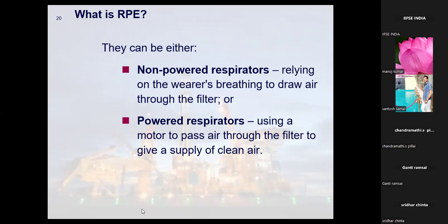19.5 is the minimum oxygen requirement level, but the quality of air, what we say is class D. Now, this class D air supply should have a minimum of 19.5% oxygen. Plus, it should not have mist. It should not have any aerosol.